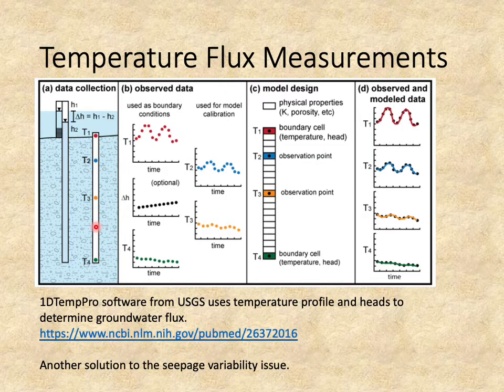The alternative that we looked at was to do temperature flux measurements. These things have been around now for 10 or so years. The idea is you put in one of your lake bed piezometers. Again, you get the difference between the head right at the lake bed interface and the head down at some distance below the lake bed. The head down here is here, the head at the lake bed is here, so we've got our change in head.